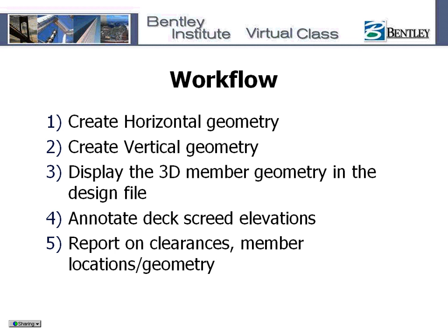So in today's example, we're going to go through just a common workflow using some data we've gotten here from some customers. We're going to first lay out some horizontal geometry representing the bridge members, the abutments and piers, the bearing center lines, the girder center lines, also some substructure locations as far as pedestals, pier caps, and footings.